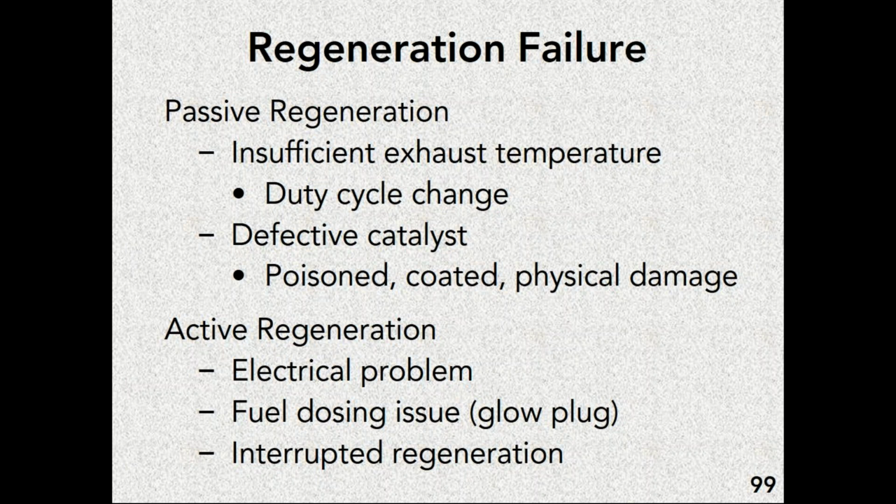For active regeneration, it's typically going to be something wrong with the actual regeneration parameter. So there's an electrical problem, so the heating element doesn't heat up. There's a fuel dosing issue, maybe a component like a glow plug or something doesn't function properly.